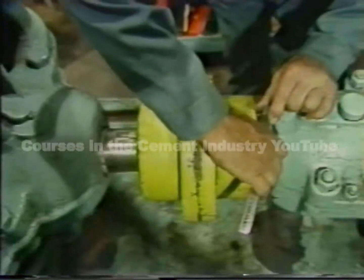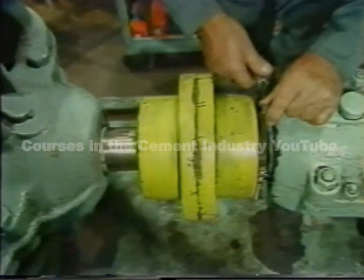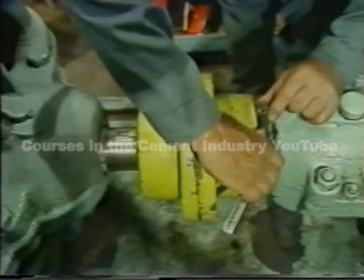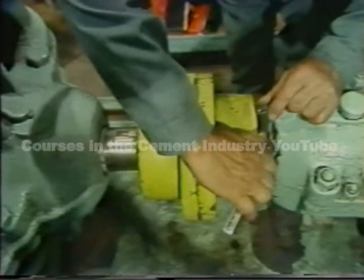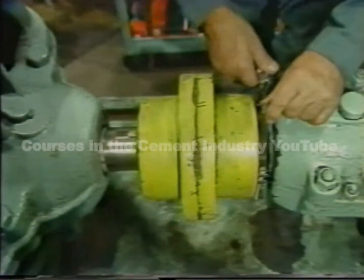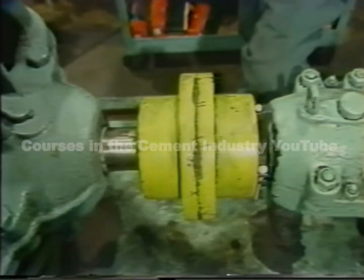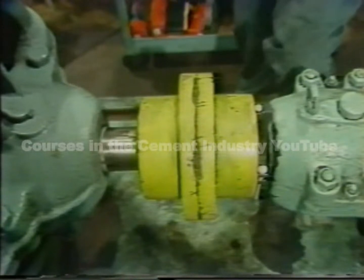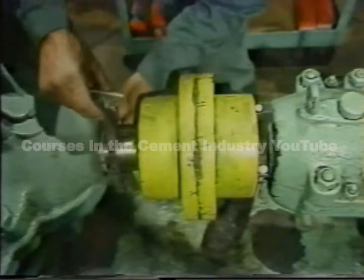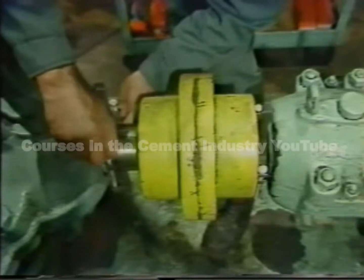When the post is up finger tight, it should be brought up snug using a wrench, or in this case, a socket extension. The idea is to get the post secure so that there's no unwanted movement. That way it will accurately indicate any misalignment on the shaft it's attached to. Next, the bracket is installed on the motor shaft. When installing the bracket, be careful to avoid keyways on the shaft. It could make the bracket wobble, giving you false indications.